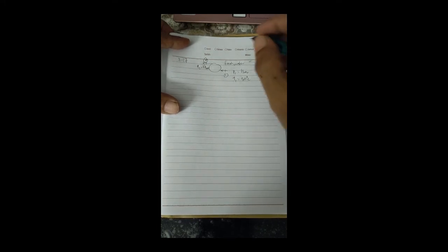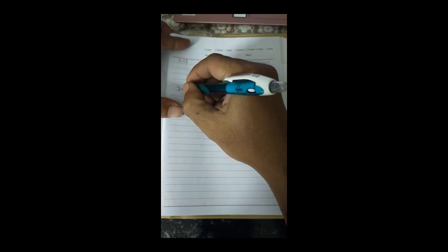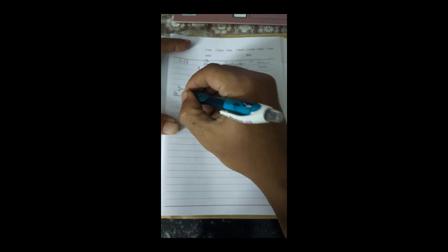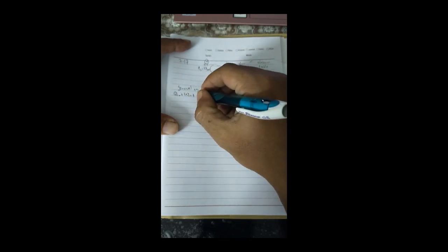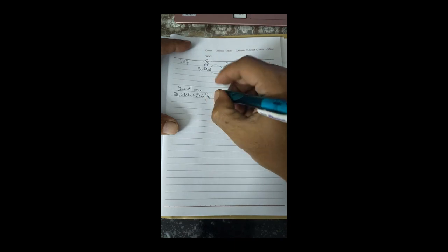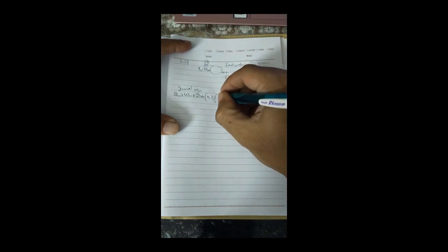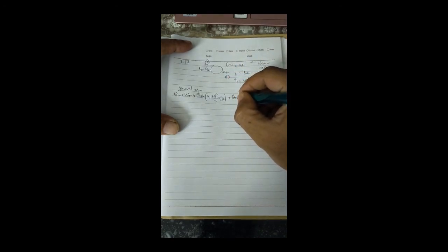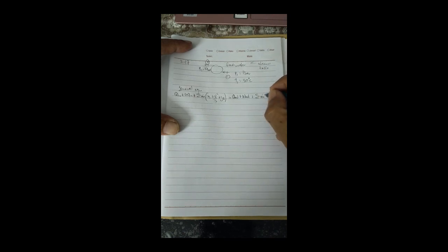General equation: Q in plus work in plus summation of mass times H1 plus V1 squared over 2 plus gz equals Q out plus work out plus summation of mass times H2 plus V2 squared over 2 plus gz.